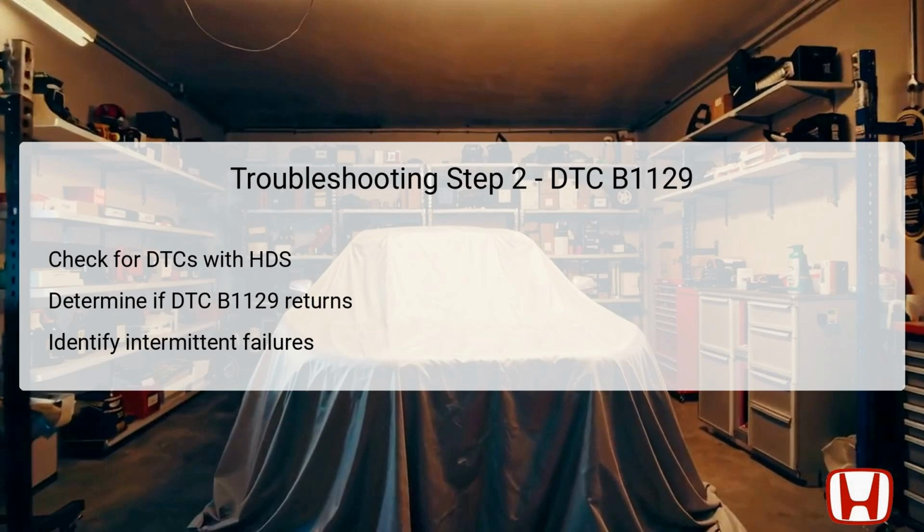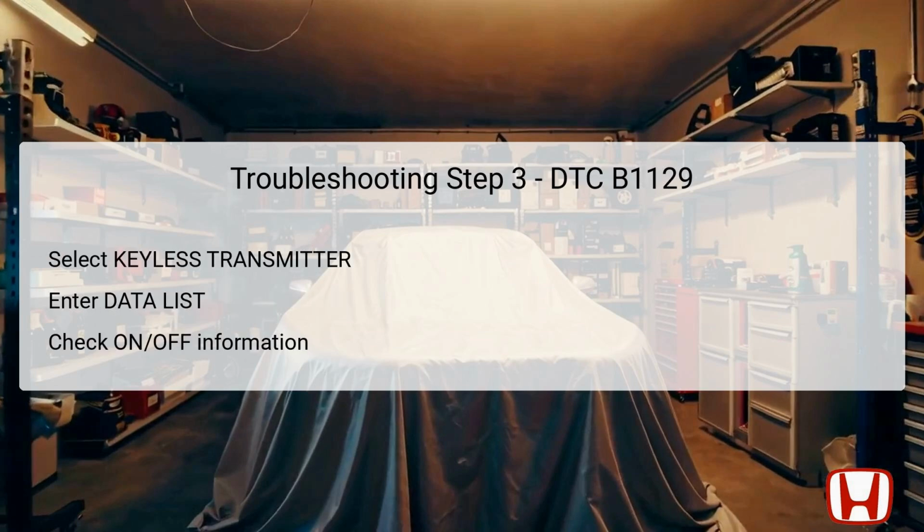In this step, access the body electrical system on the HDS and select the keyless transmitter option. Move to the data list where you can check the on-off information for the driver's door lock knob switch.